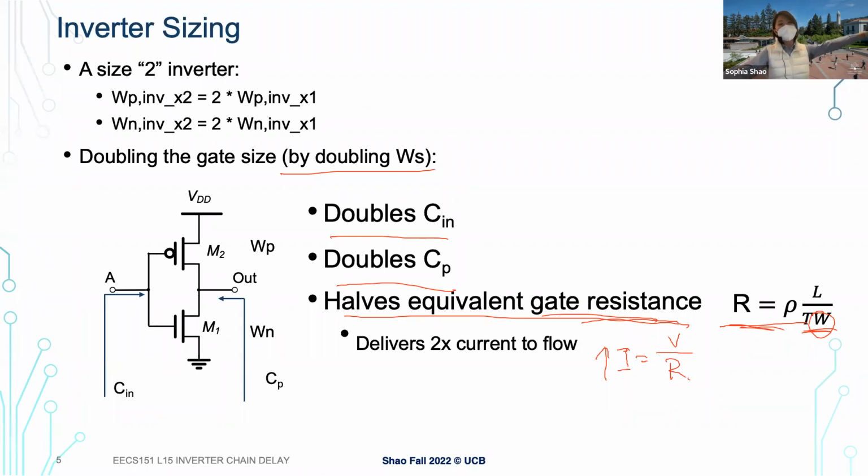But definitely the parasitic capacitance is also bigger, so that's also a factor when we think about it. So there is a trade-off there. You make the resistance smaller, but the parasitic capacitance, which we need to charge and discharge, also gets bigger. So there's a trade-off there. We'll see the relationship in a minute. Any other questions?